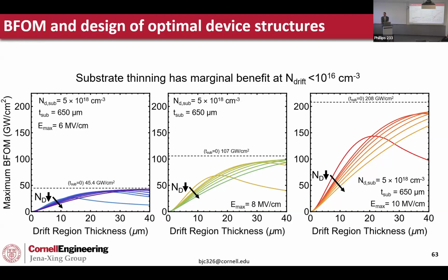Kind of, but it's not a huge change. In this case, what this plot is illustrating is that in terms of the total resistance of the device, the substrate is about 5 or 10%. If you want 5 or 10% less resistance, then yeah, you can thin the substrate, but I'm highlighting the trade-off there. Of course, with heat, you can do microchannels and all that, which is slightly different. The math will be different.